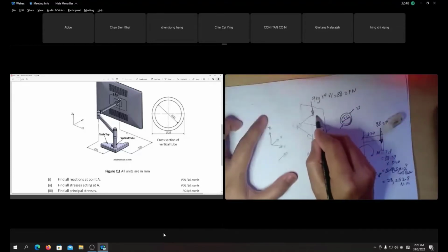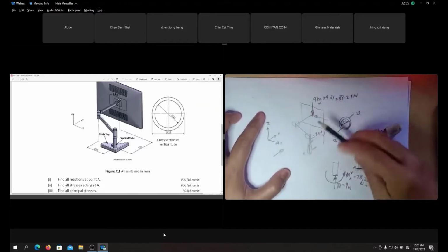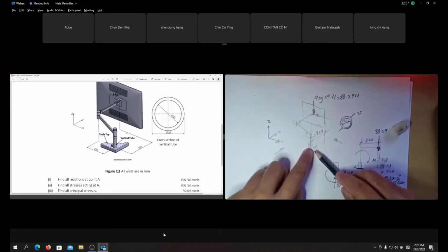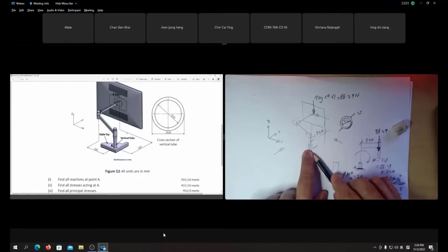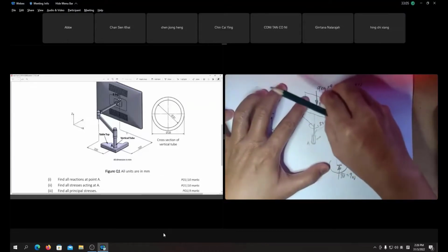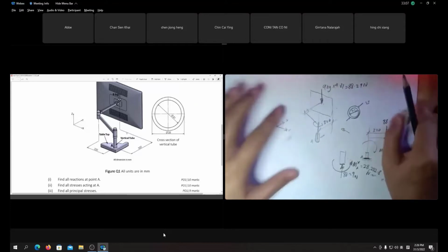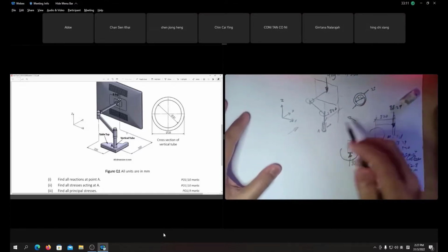Unless you have a force like this, not vertical but in the X direction. Of course, then we have torsion, and also we have moment in terms of Y. We don't have moment of X. Okay, let's zoom into this question. The force is vertical downward, so we don't produce any torsion at the tube. No torsion at all. But we have two moments.